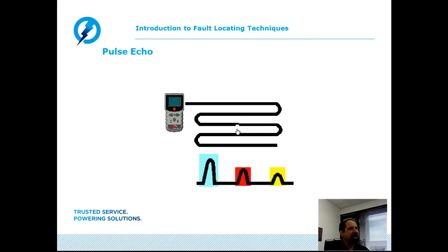the cable. The red, we show kind of a partial open in the cable, but again, we still have some continuity. We just have a much higher resistance at this point in the conductor. And then we show the end of the cable as an open circuit, where all remaining energy that's transmitted can't go any further, reflects off the open and back to the time domain reflectometer.